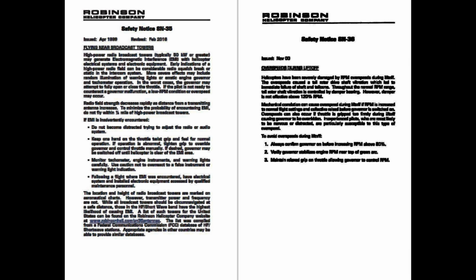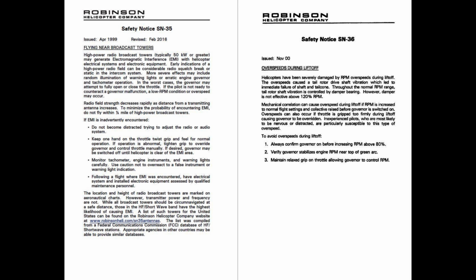What can cause an overspeed during liftoff? Gripping the throttle too firmly or not turning on the governor. What might abrupt control inputs or accelerated maneuvers do to the helicopter at high speed? They may produce high fatigue loads and over time could lead to failure of a critical component.